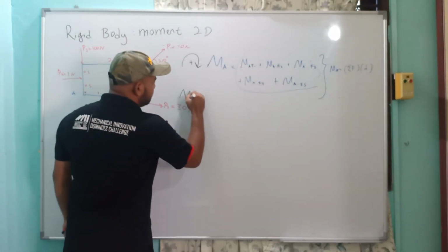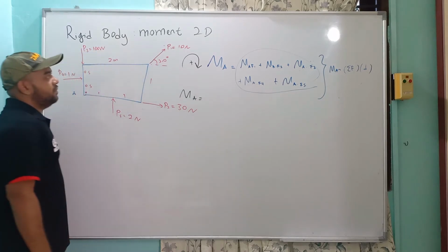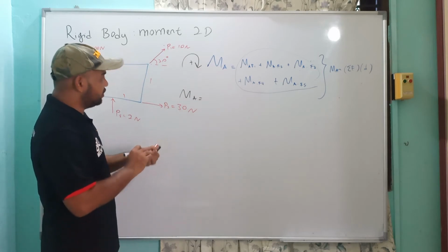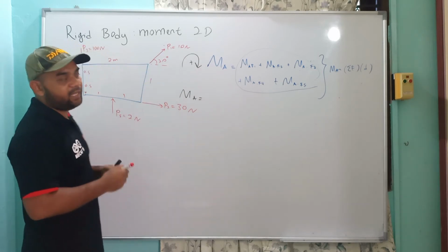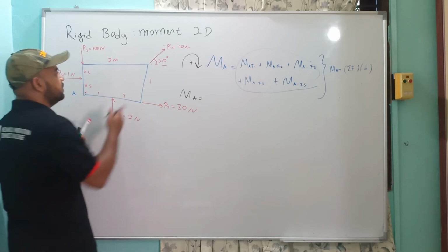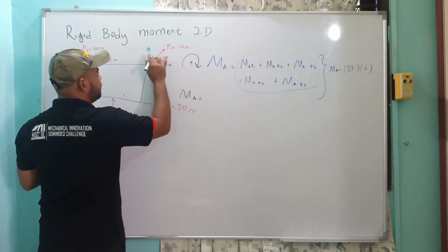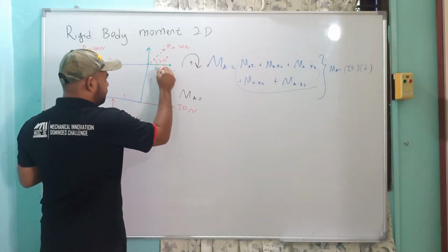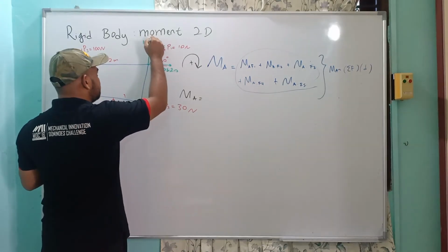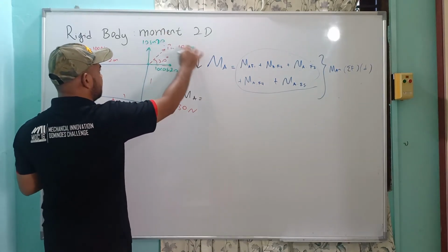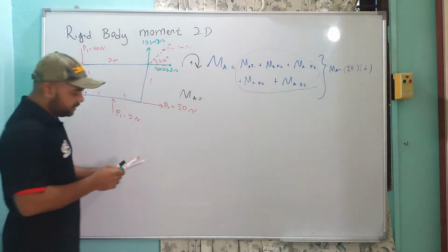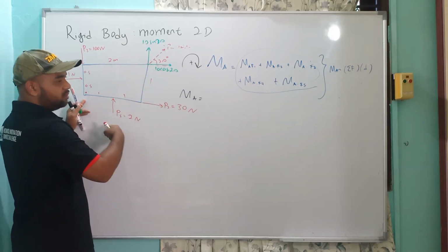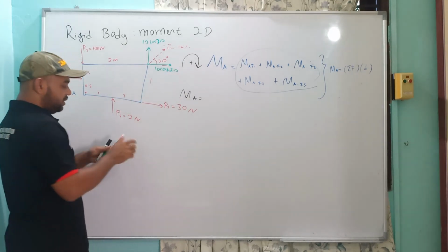So moment at point A, the first one, M because of the first one. The first one we get the angle, so like previous, I can resolve into two components, this one and this one, so I can erase this one. So this one P1, which is 10 cos 20, 10 sin 20, so I can erase this one. So because of the first one, put the pin here, I pull this direction, so it will go clockwise. So because of this one, it will be positive.